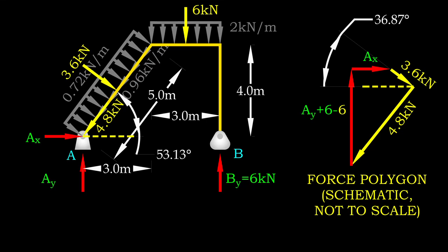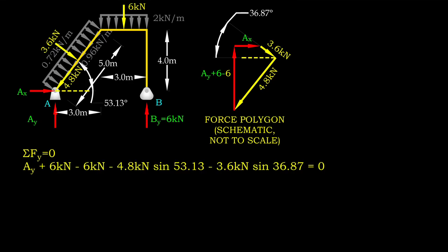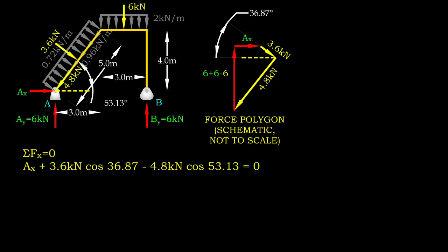Let's extract the forces and reactions, namely Ax, Ay, and By on structure and form a force polygon. By taking equilibrium in global y direction, we obtain the y component of inclined loads. Then, we use it to construct equilibrium equation with our resultant vertical reaction. As a result, Ay equals to 6 kN. Similarly, we construct equilibrium equation for global x direction and find out Ax is 0.